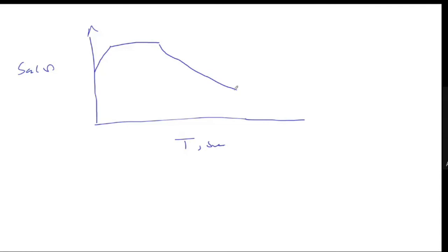But if you look at the IBC, in IBC there is also a fourth branch. In UBC it is just decaying with the same trend, but in IBC the trend changes at a time period that is called TL.